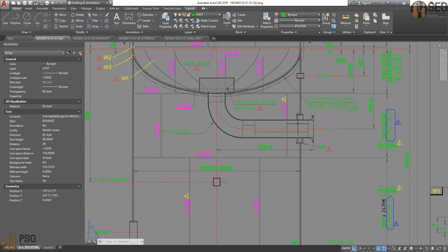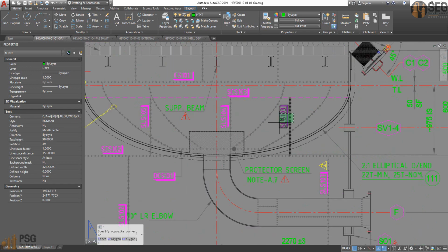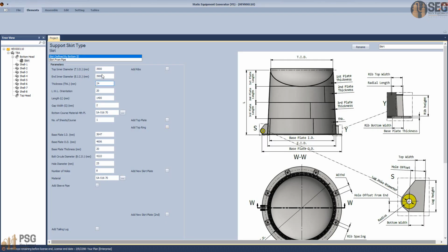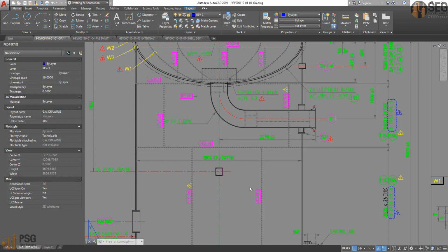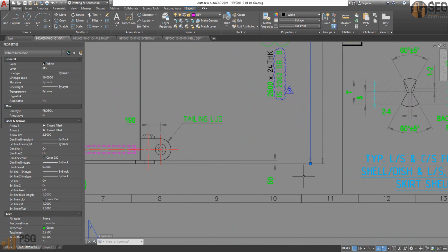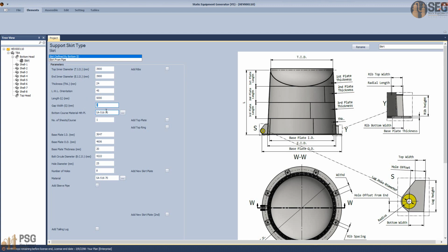So how to add those cans to SEG, and one more thing, which is how to define the longitudinal welding line orientation per each can. Okay, now let's come back to SEG and fill those values. Here, the first longitudinal welding line orientation on the bottom can, the last one here, it's at 24, and the total length of this can is 5 meters. Let's take a look at the drawing here. The total length of this can from the tan line to the bottom of the base plate is 5 meters. So the total length is 5 meters, and here the gap, let's keep it 2.